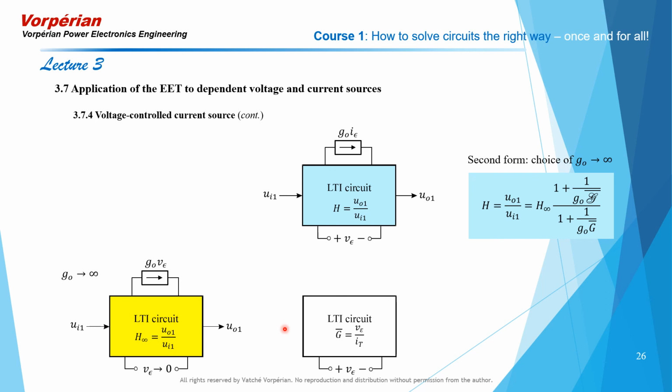Next, you compute the inverse gain with respect to G0 with the excitation set equal to 0. But this is exactly the same thing as we did in the previous slide for the case of G0 going to 0. And I repeat, the inverse calculations, whether it's null or ordinary, are not affected by your choice of your extra element, whether you take it out as 0 or you take it out as infinity.